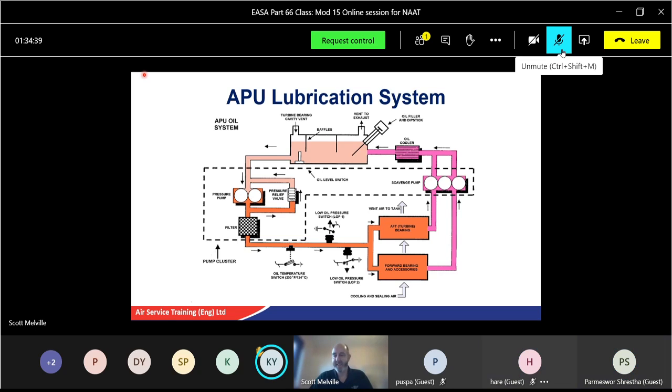We have 2 low pressure switches, yeah. One is to allow ignition and fuel flow. That's the first one, it opens at 4 psi. If it senses pressure at 4 psi, it will allow the ignition and fuel to continue. And the second one, when the pressure builds up, provided the first one senses 4 psi.